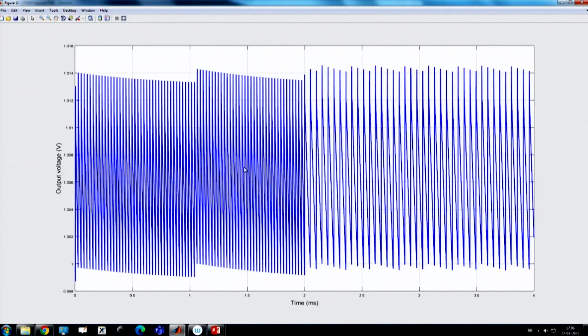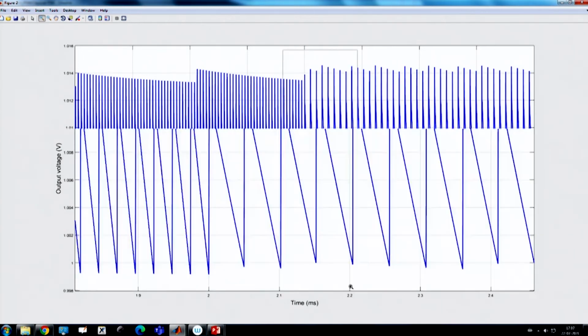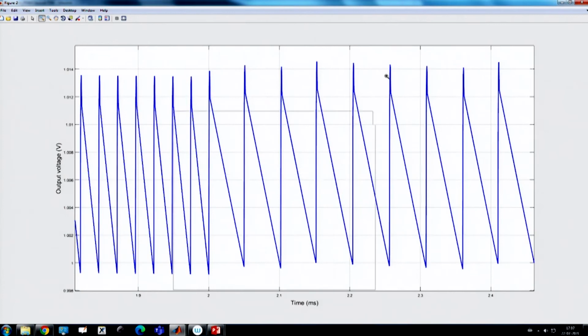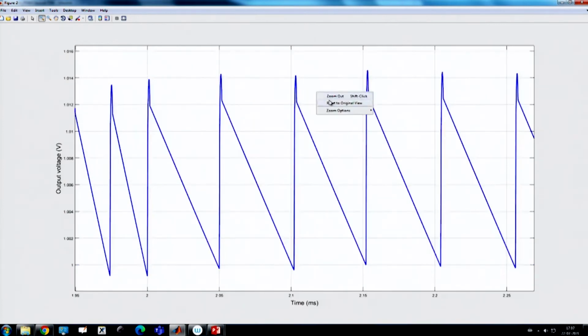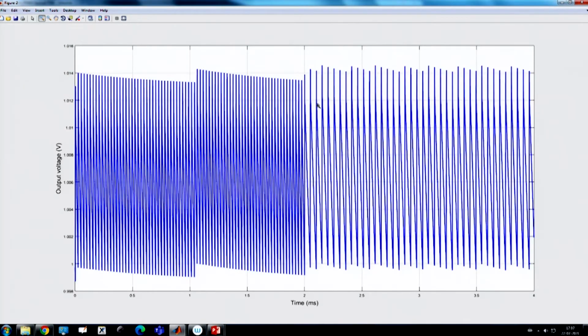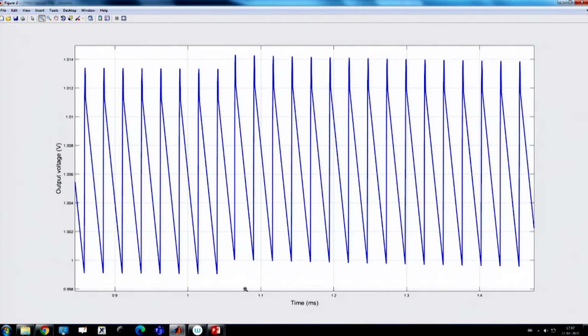Another thing you will find here is that there is a charge pulse, and if the load current decreases, more skip cycles happen. But this pulse skipping modulation has a problem of non-monotonic spectral composition. The number of charge and skip pulses may not be exactly balanced for any arbitrary load and input voltage condition, and if they are not balanced, then after a subsequent number of charge and skip pulses, it can undergo an additional charge pulse or additional skip pulse.